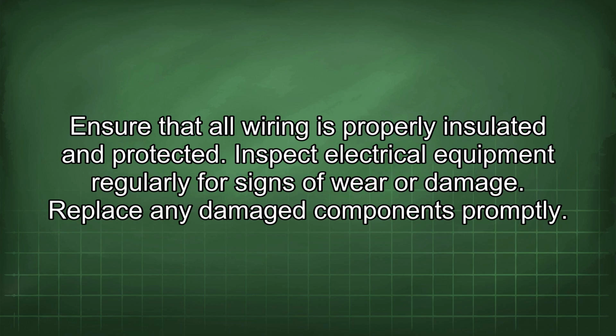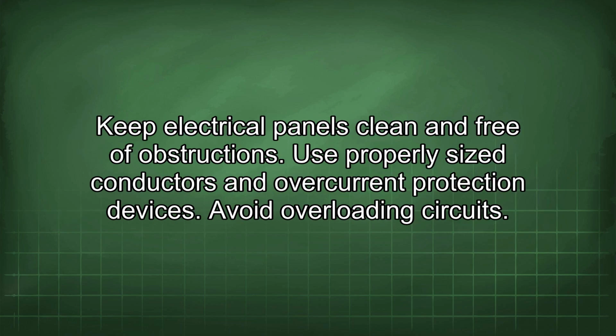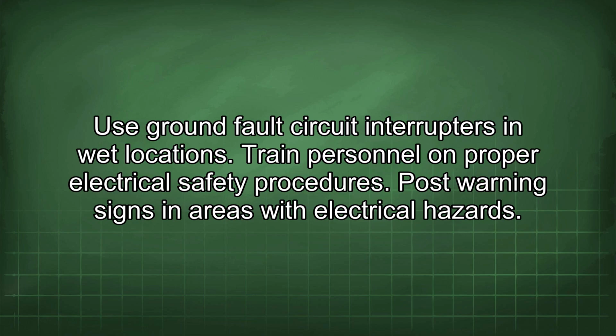Replace any damaged components promptly. Keep electrical panels clean and free of obstructions. Use properly sized conductors and overcurrent protection devices. Avoid overloading circuits. Use ground fault circuit interrupters in wet locations.